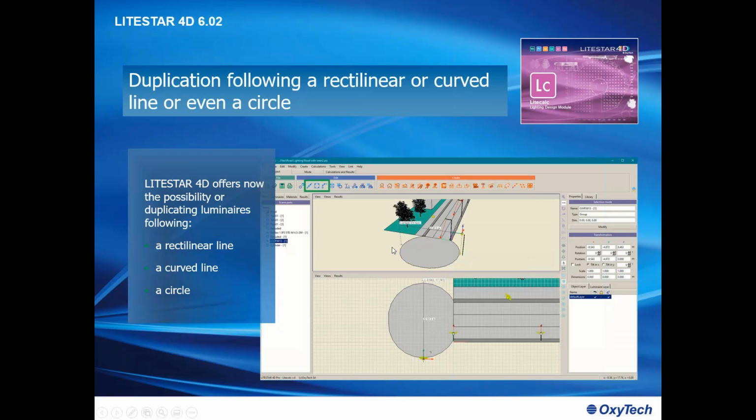Simply defining the radius, or the diameter in the case of a circle, the circle will appear once confirmed, and you can move it to correspond perfectly to the roundabout you are studying. Or, if you have a road with a curve, you can follow exactly the curve, and once you confirm, the program will ask you how many luminaires you want to place, and automatically the program will display the luminaires along the curve.